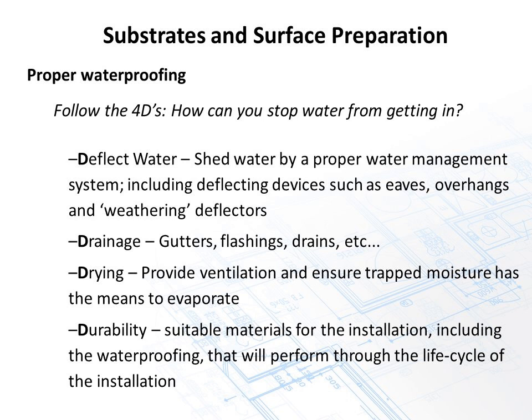That the installation can dry. Is there proper ventilation? We want to make sure that we don't have moisture trapped, that it has a means of evaporating. And durability, the suitability of the materials for the installation, meaning again the tile, the stone, the setting materials, the grout, etc. Make sure that they can perform through the life cycle or anticipated life cycle of that installation.